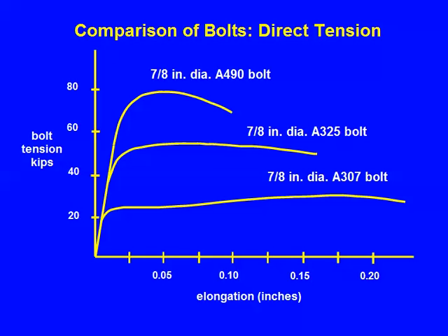But clearly for the other two types, in these regions, there is no yield point. It's a high enough strength steel that doesn't show up. And that's typical of high strength steels. And why is this important? It's important because we have to appreciate that there's no basis for design that relates to yield of the bolts. I'll come back to that too.